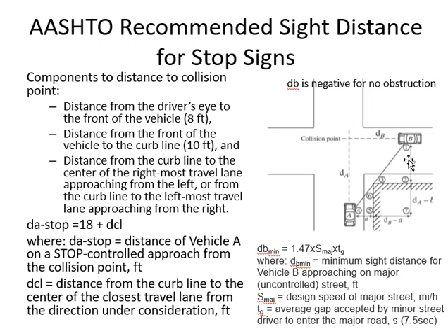Now you see the problem. If this guy is standing here and he can only see 300 feet, then whenever he decides to go, it is unsafe. Because he needs how much? 500 feet, right? And he can only see up to 300 feet. So it's unsafe now. Okay? Clear? So when there is a stop sign, this guy is standing at the stop sign, looking at the cars coming from the other road. Whatever gap he requires, he should be able to see the distance which the car covers in that gap.